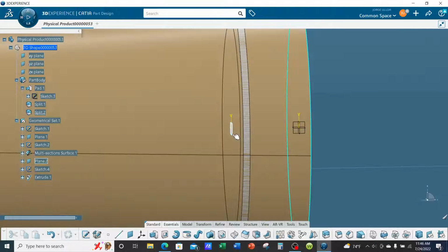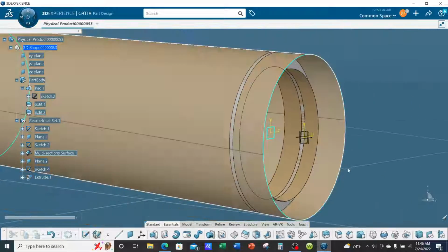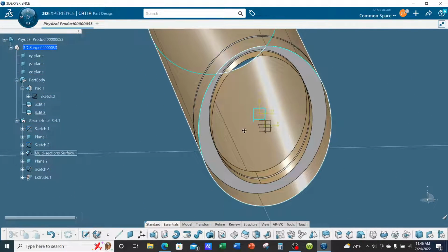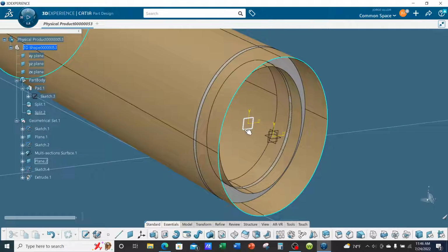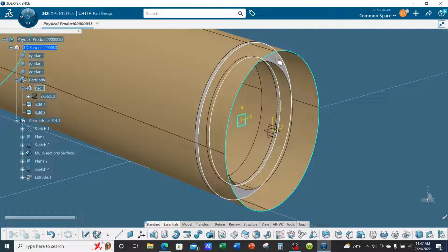Okay, so you can see that the plane is on the back side, or aft side, of the solid. You can see that. All right, so what I'm going to do is create a new plane offset 1/2 inch, because we're going to leave the inside, the web area of the frame, at a 1/2 inch thickness. Currently the solid is 2 inches thick.